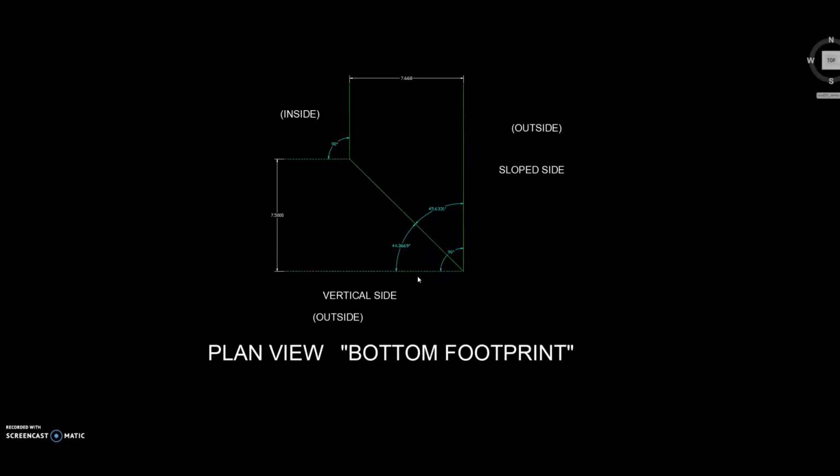With the bottom footprint done, from where we got the compound miter angles, now we're going to make use of this and start working toward getting the compound tilt. Needless to say, a footprint in this case is a horizontal plane cutting through the corner. With that in mind, we'll create another footprint, which we'll call the top footprint, because it's going to be a horizontal cut or section at a higher point than the bottom footprint.